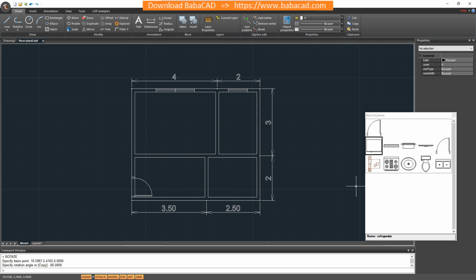Also, we have an interior door block, which is a bit smaller than entrance door. Double-click to select the interior door block, and insert it in the drawing. We have to mirror this block, as we need opposite door opening angle. I'll use Mirror command. For the Mirror command, we have to specify 2 points to identify mirroring axis. Then, just move mirrored block to the position of entrance to the living room.